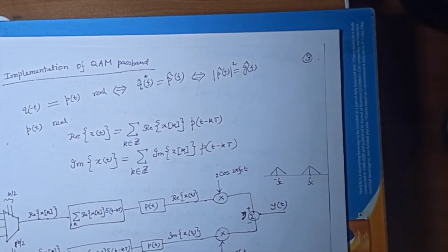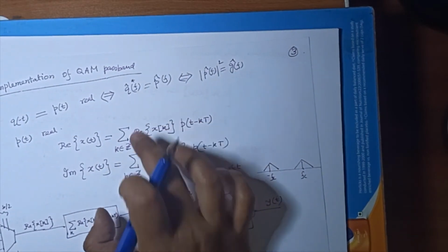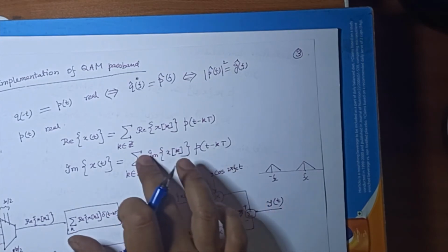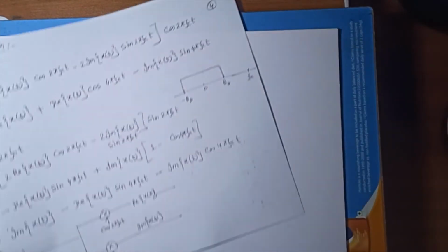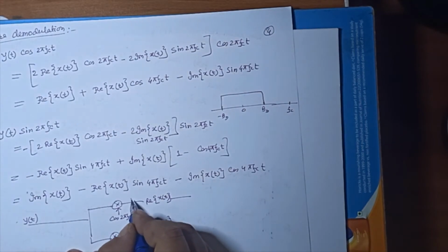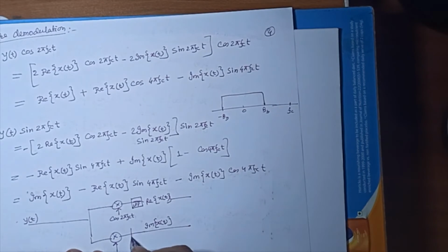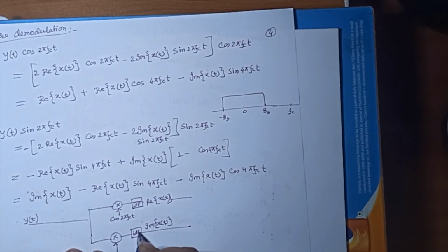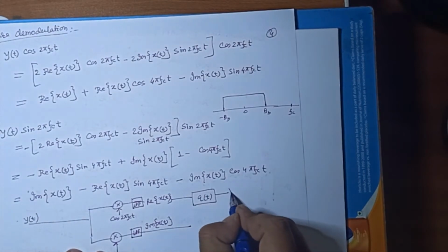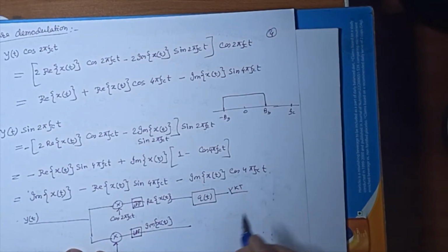So I can do matched filtering after that, which will give me this value. This is also a real number with a real pulse. So do matched filtering to get these values. That will work. Before that I have to do low pass filtering, which will give me this, and then I will apply the matched filter. So this is qt followed by a filter followed by a sampler.